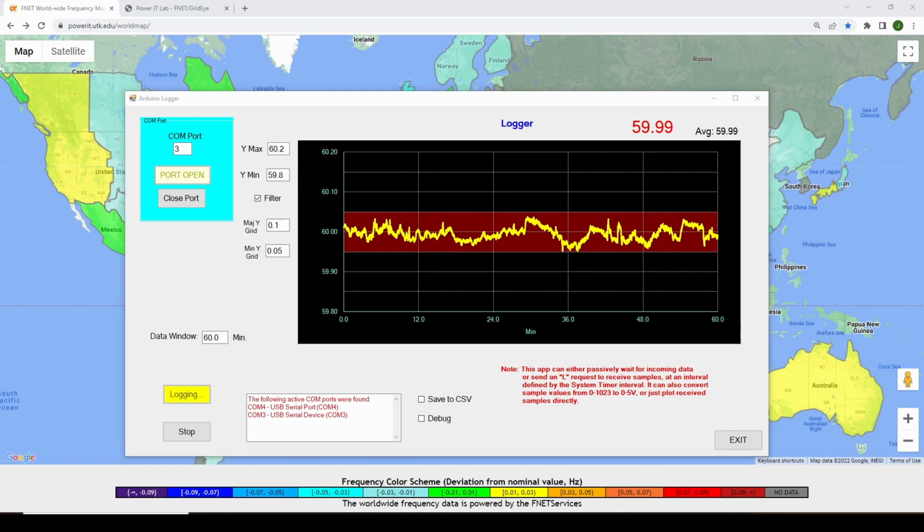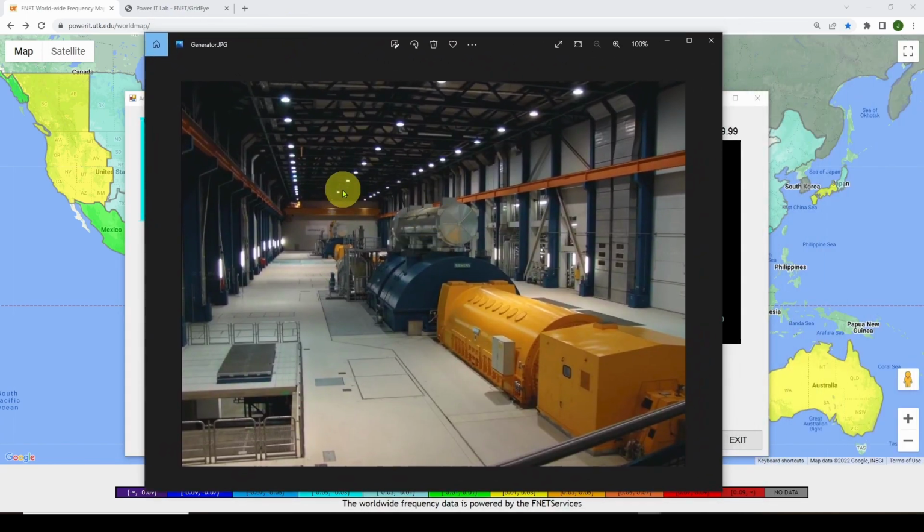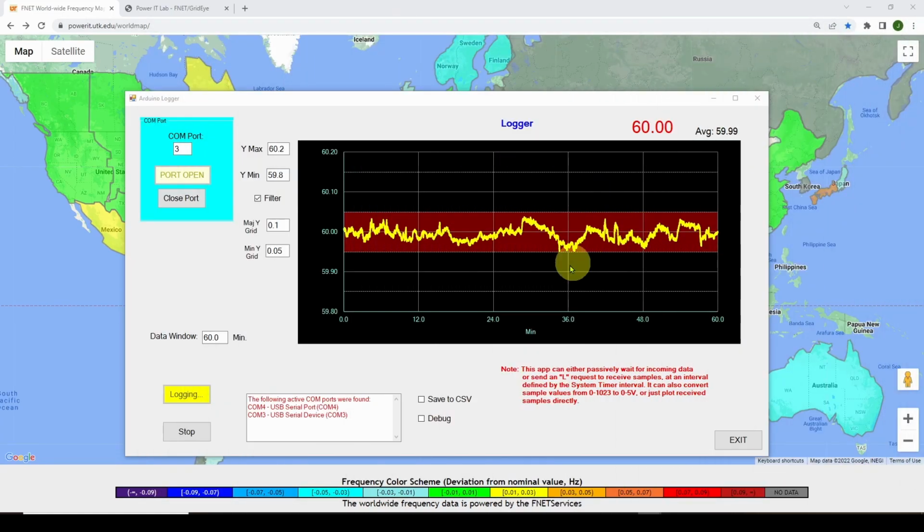The way they do that is they monitor the frequency, and if the frequency is getting too low, you send a signal to this generator that says, hey, add more steam to this turbine, get this thing running better because it's slowing down and we're running out of energy, you need to speed up. And conversely, if it's going too fast, hey, slow down. So there are some very complicated control systems involved in all of these generators that make sure that you are operating in a very tight range of frequency.